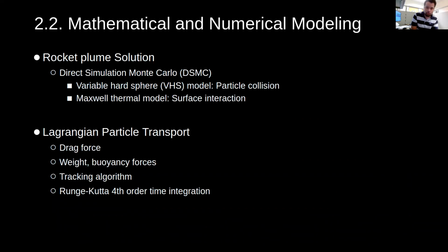The DSMC model considers computational parcels representing statistically several molecules to solve intermolecular and molecular surface collisions. In the present investigation, all simulations use the variable hard sphere molecular model for binary collisions, while the energy exchange between particles and wall surface is solved by the Maxwell thermal model.